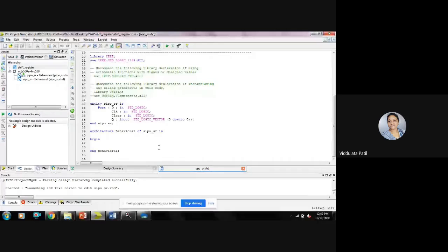this parallel out shift register. Okay, so here, as we want to process this signal in a sequential manner, we will write a process here, to declare a process, and the sensitivity parameter for this is the clock. So depending on the changes in the clock, the statements in this process are going to be executed.